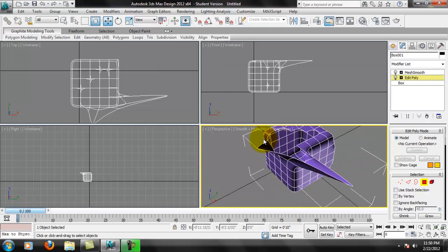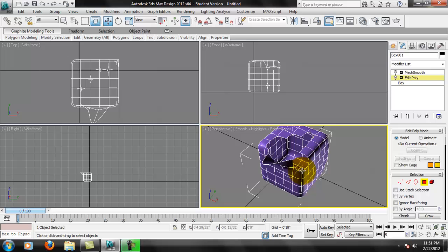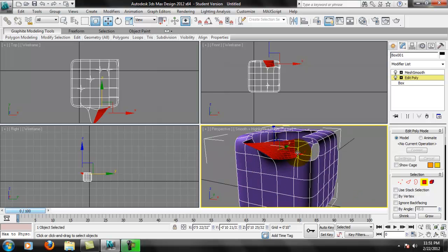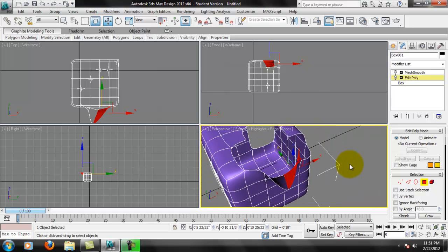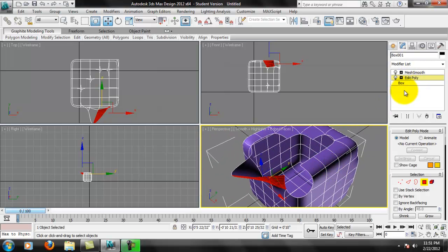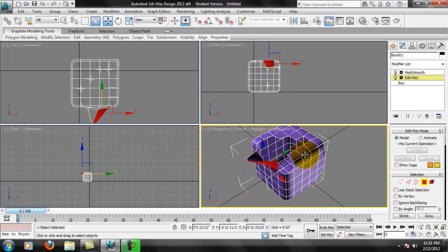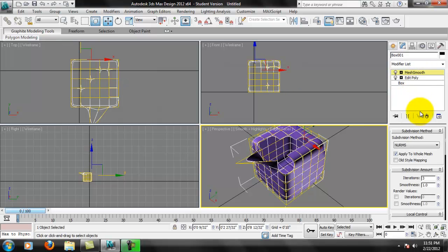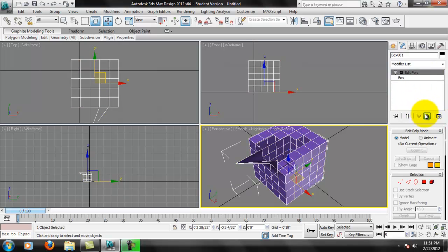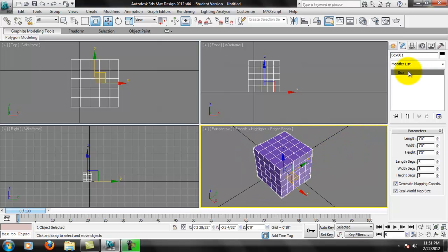So again, we're not going to focus on this today in this video. I just kind of wanted to show you in case you want to be adventurous and you know, experiment with this. This is kind of where the modeling side of it's headed by creating our organic models through here. Okay, so I can delete these if I want to and step back. So if I would have converted that to an edit poly, I would have been stuck with that, but now I can delete this since we use a modifier stack.